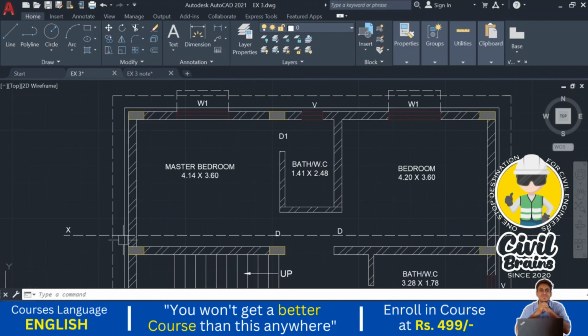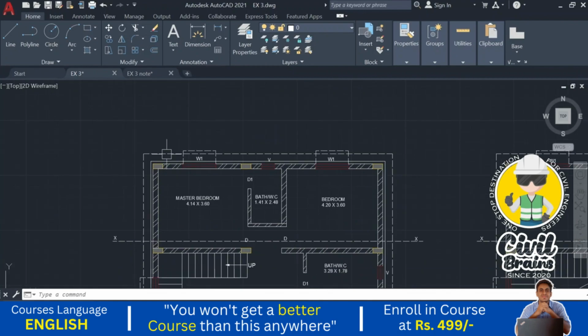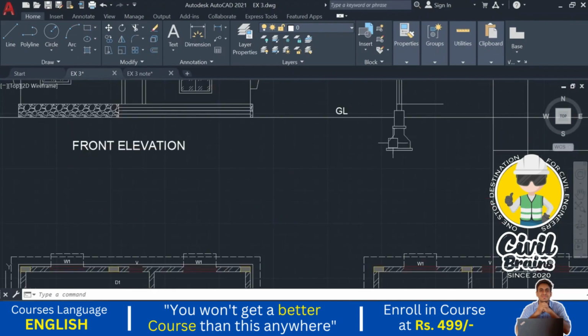So this is the foundation. From this column to this column we need to provide this foundation, the above one. And the below one, this isolated footing, is only where the column is. It is not running over the walls, only where the column is, it is there.